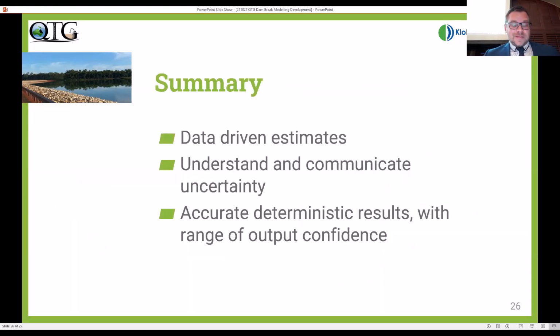In summary, we've explored the pertinent inputs to our dam breach models, and I've spoken about how we've traditionally estimated these inputs, how we're currently working to reduce that uncertainty and recognise the variability in results, and what I think we'll be working on in the near term to further improve our assessments. I hope that providing this overview can remind us that the assumed inputs with a great model are still assumed inputs. And are we suitably communicating that level of uncertainty through the reports to our clients?